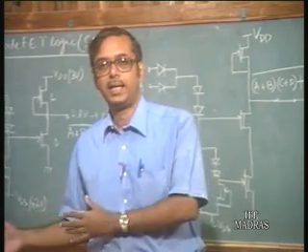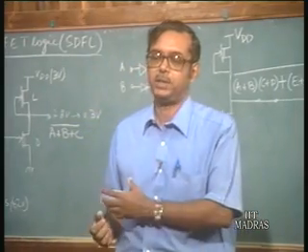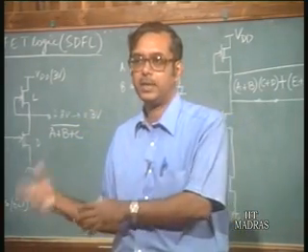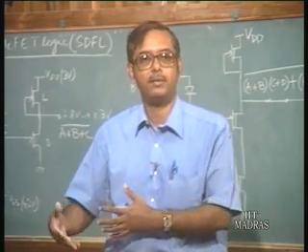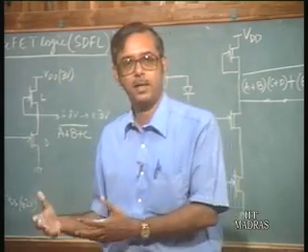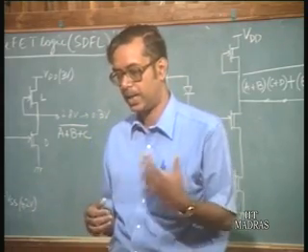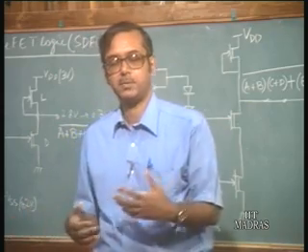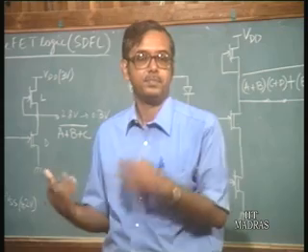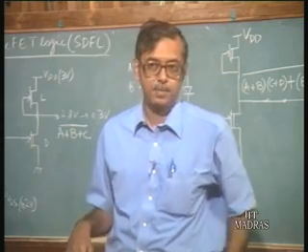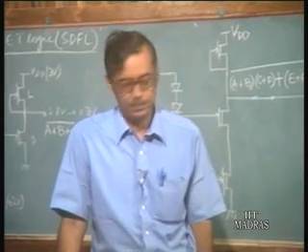On the other hand, these logic families which we discussed today, which use only depletion mode transistors, do not require such complicated technology, but you have to pay for it. They are not as fast as the logic circuits which we discussed last class, that is using both enhancement mode and depletion mode, and of course you have to have two power supplies and usually more transistors. So that way there is a trade off. So this is about the FET logic family.